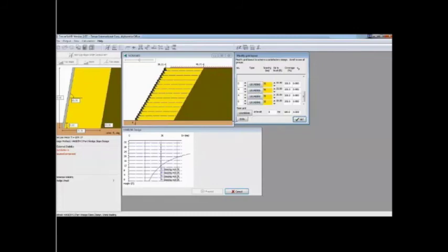But let me change some of these geogrids. You can see it's saying the spacing is not okay at 36 inches of this geogrid. I'm going to change one of these geogrid layers in this group as well to UX 1500. And I'll change a few layers so maybe I can explain this better for you. The 1500 curve is here, and it's saying that the 1500 can be spaced at elevation 0 at 36 inches, and it will be suitable, just barely. It almost comes exactly to that point.